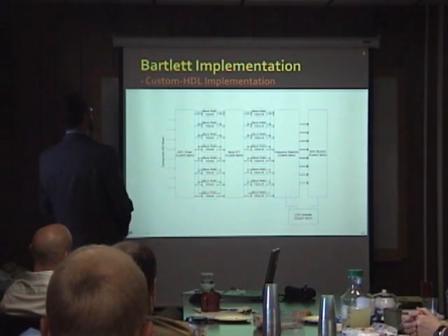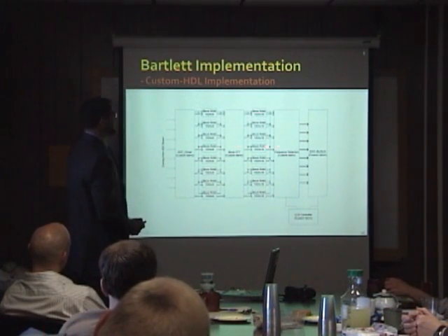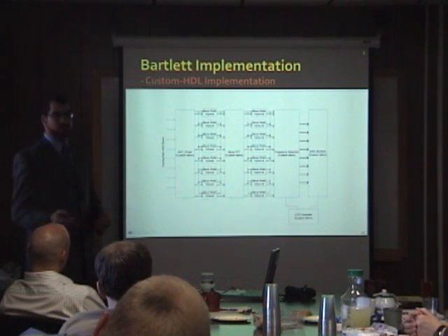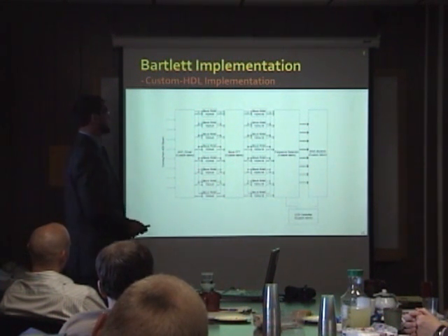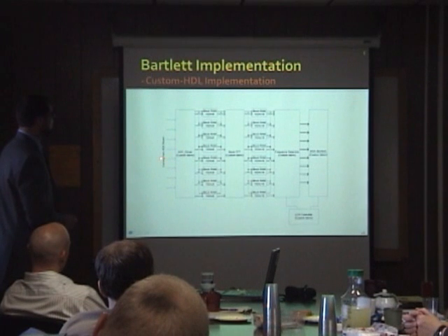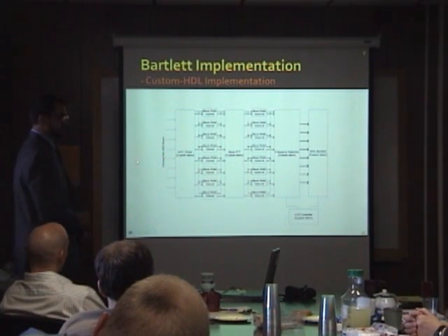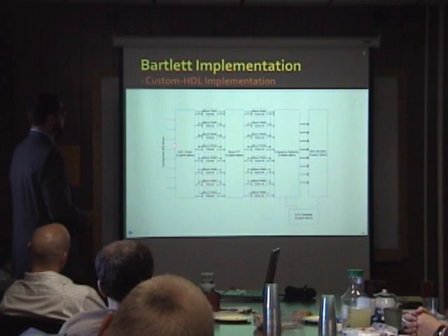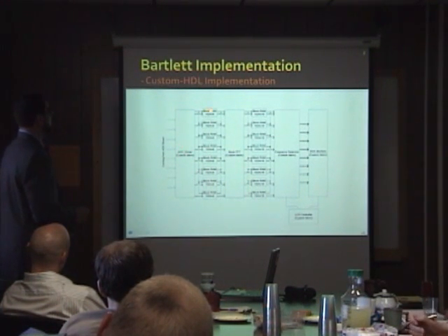So the first implementation was the custom HDL implementation, which is usually referred to as the hardware implementation too. The ADC driver here is connected to the ADC board and receives the signals. It also configures the ADC board through a SPI line or lines. Once the data starts streaming in, this ADC driver packages them into bytes and stores them into